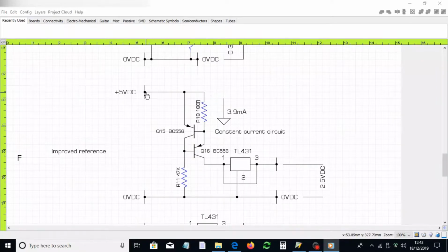So again, it favours going slightly below the minimum of plus 5 volts DC, bearing in mind that the TL431 outputs 2.5 volts DC. So this is the circuit that I preferred. Bearing in mind the source circuit would need a mirrored version of this circuit, effectively we need two TL431s.